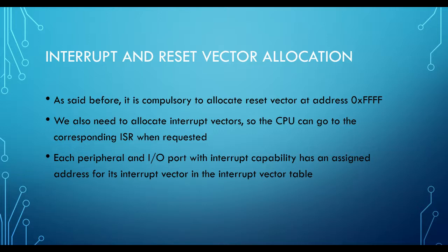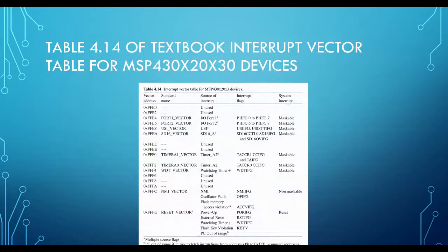Each peripheral I/O has an assigned address. So you can see that each of these devices has an address. In the case we are not using this model, you need to look up which model you're using, and there is a reset address. But most commonly they are the same. So you have to define this, the reset table. This information allows you to look at where the reset address is. It's permanently stored at this section.